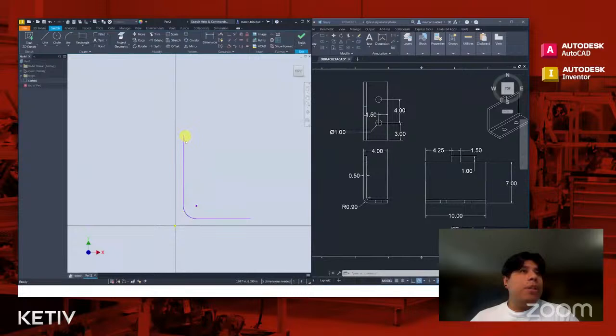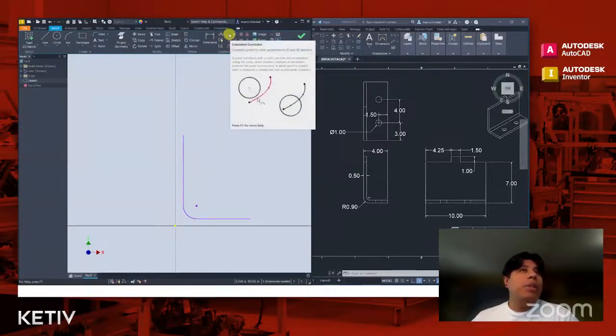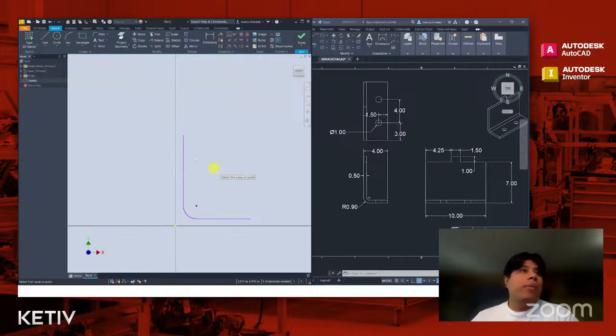Now for me, the first thing I'm going to do is place this so that my origin is better positioned on my bracket. So I'm going to go up to the top and constrain with a coincident constraint. And I'm going to move this left point of my bracket and put that over the origin. And that'll just help me as I start to constrain this. Now I have a grounded point to where I can measure and dimension off of.